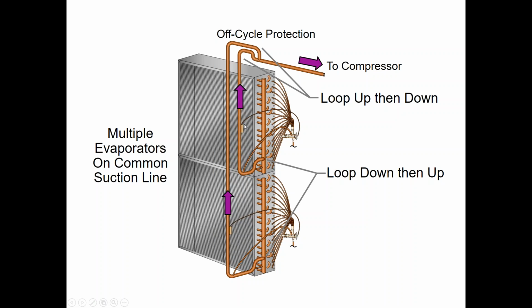Number 2, we need to think about the TXV sensing bulb mounting point as well as the equalizer tube. So think about that. Now, for drawing's sake, that's just where this equalizer tube ended up. Don't ever put the equalizer tube in an elbow.